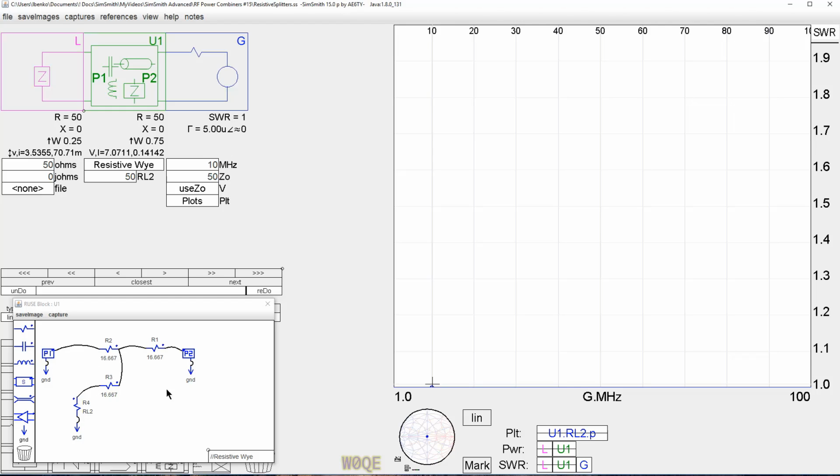However, I lose a 1/2 watt inside this splitter. That's okay. The resistive splitter is a very nice circuit. It's very flat with frequency, and it goes all the way down to DC. So it's a circuit you can actually buy, and it's quite useful. It has very little isolation between the ports, but that's the way it goes.